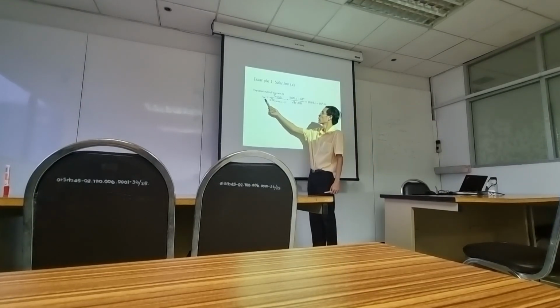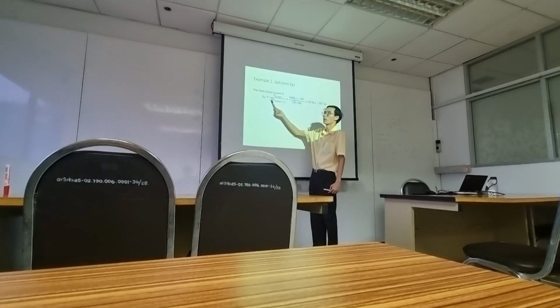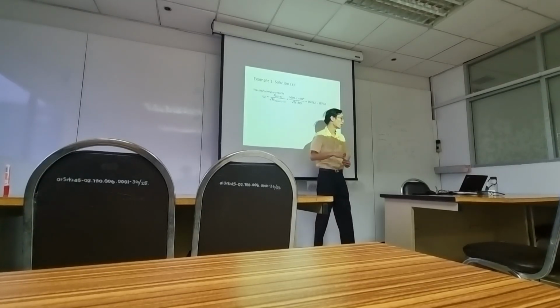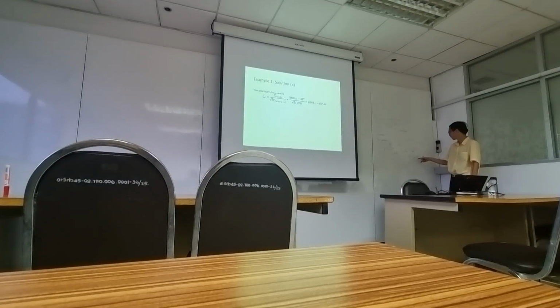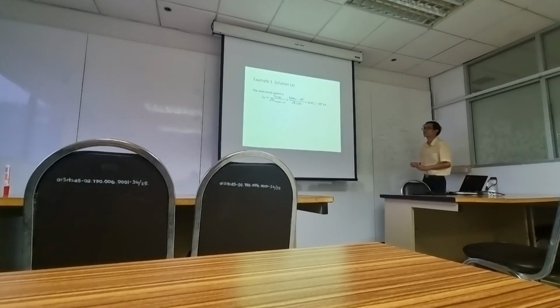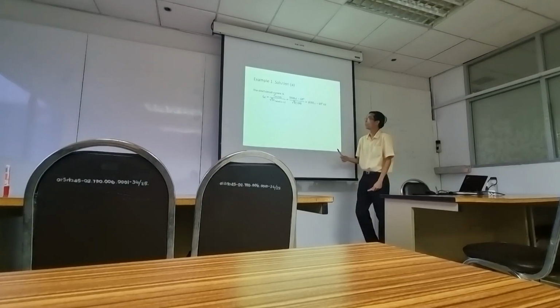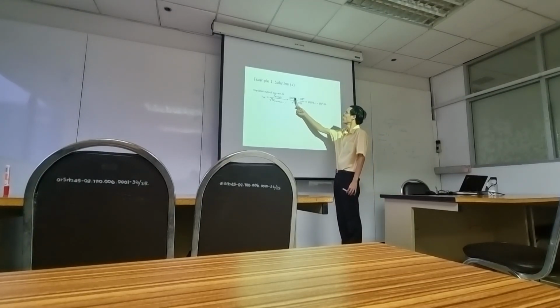So the short circuit current is SSC conjugate divided by root 3 and then V rated. I just want to make sure that the angle is 0. The short circuit capacity is this one, and then root 3, and the line to line rated voltage is 138.